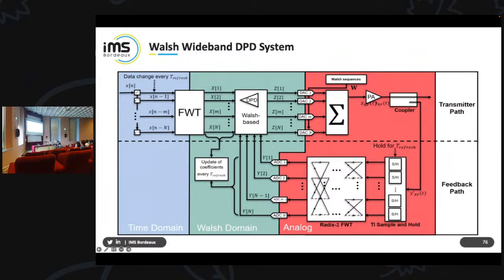Yes, if the PA impedance changes, the PA can be abnormal in a high variation load. That's true, so the load modulation is required. For the load modification, it's what I've called the output matching network. That's why we still need some physical implementation of variation, for instance one capacitor here and there to modify the impedance. It can be controlled by digital words, by the circuit itself, to dynamically adapt and find the best trade-off for the energy efficiency or the spectrum access.